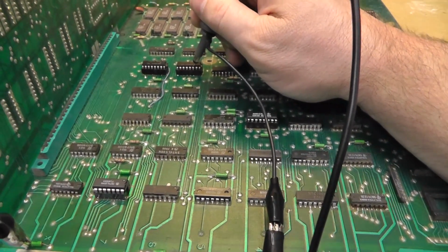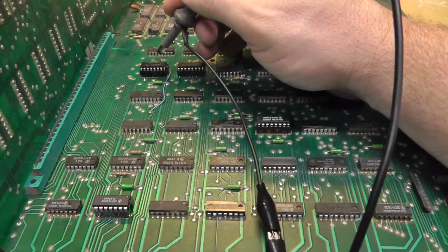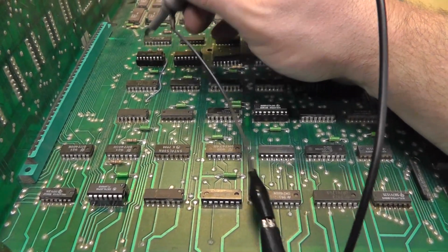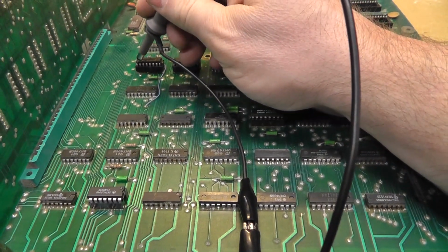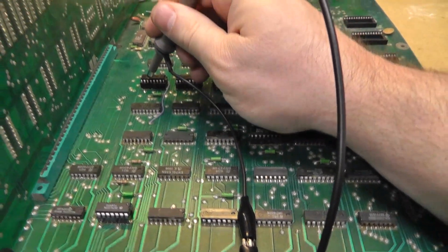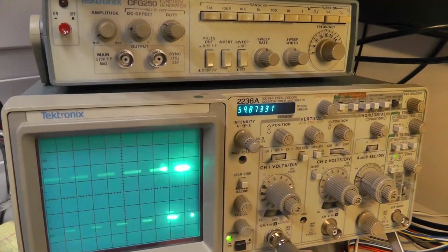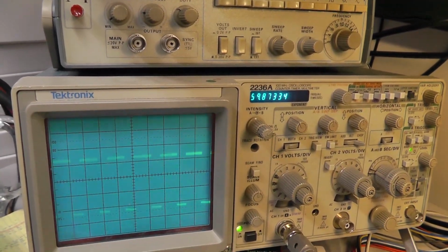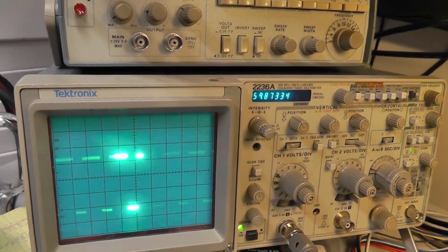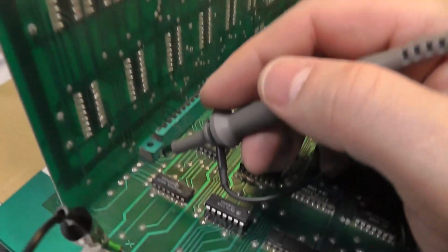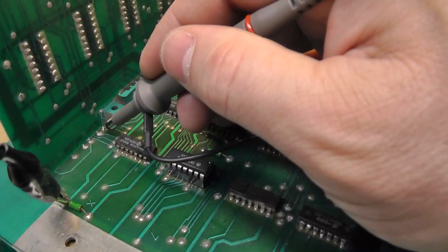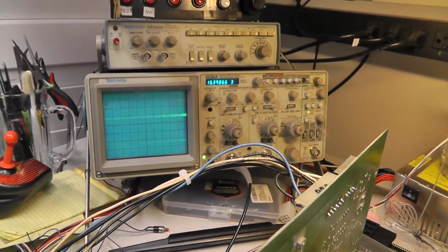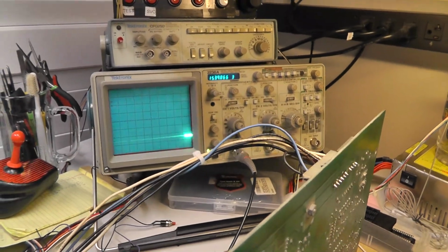Got a frequency measurement on here. Actually, we're going to go to pin 11 of E7. 9, 10, 11, and we should have 60 hertz. And we basically do. And if I come to my two resistors, this one we were getting, I think, 15 point something K. You can see that.